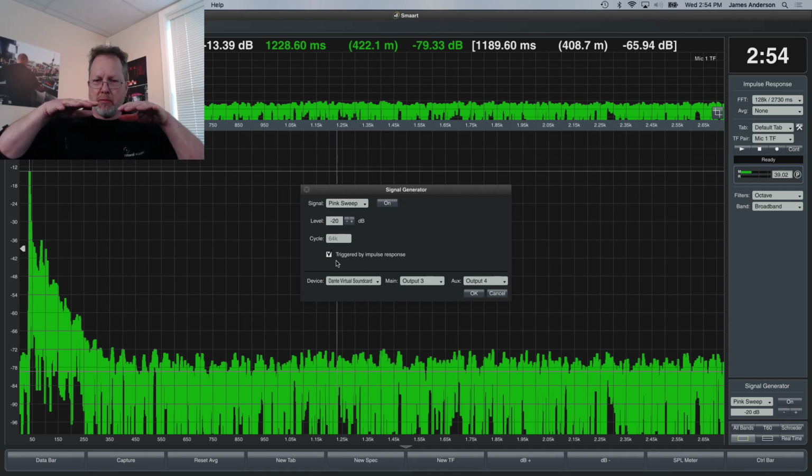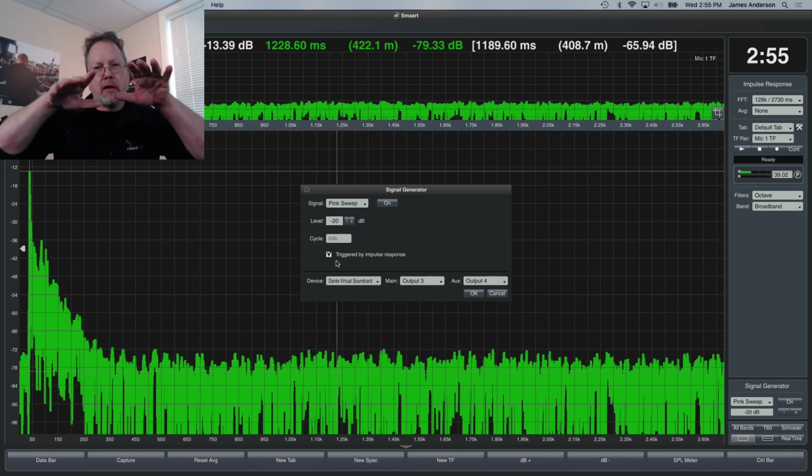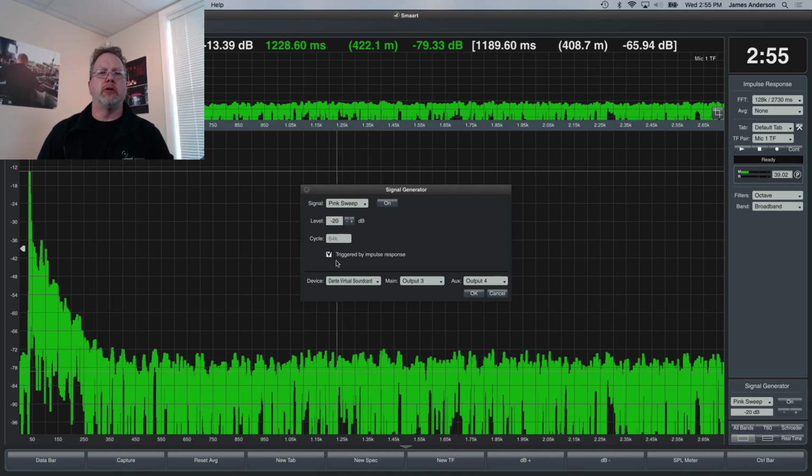Now, with complex noise, when we're taking a measurement, that's just going to be one of the things you'll see where your systems have more harmonic distortion, measurement to measurement. I'm hypnotizing you. Measurement to measurement, you're going to see some flutter and wiggle in your trace, because every time you take your measurement, you have a different combination of low frequency to high frequency, and so you have different amounts of harmonic distortion. The way that we deal with that is statistically: we're going to average our measurement and get the statistical response.